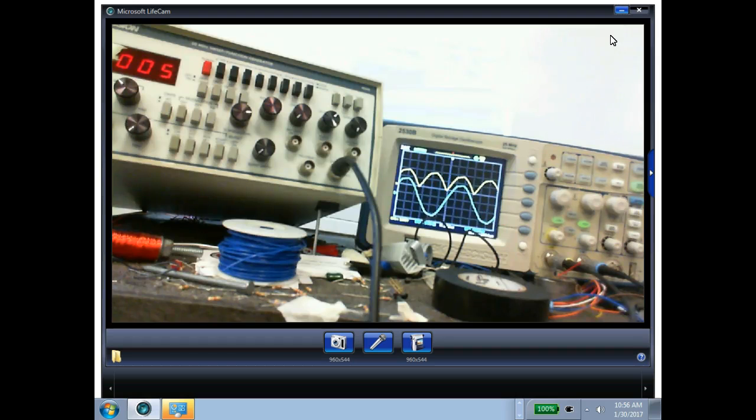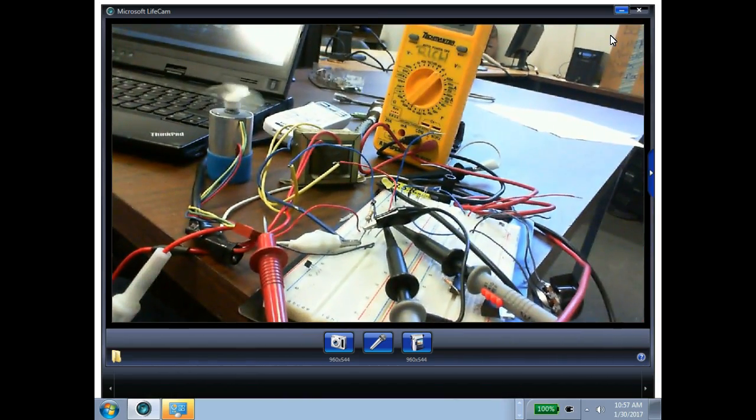Motor's not going to run as fast, of course, but it's going to run smoother. I should let y'all come up here and listen to the motor. A while ago, the motor had a hum. It was running fine, but it had a hum. We're not going to pick up anything on this because now it's going to be really smooth because this is getting full wave. Right? Y'all probably can't even hear it now. Well, it's running smooth as silk.